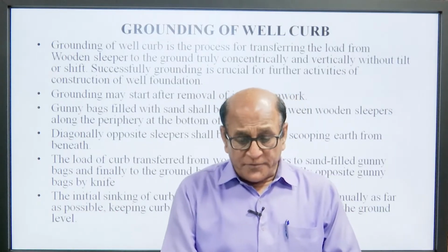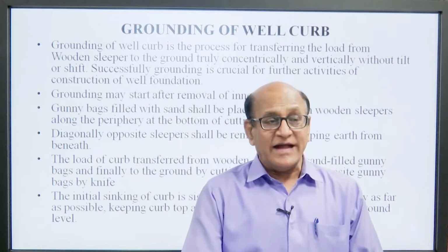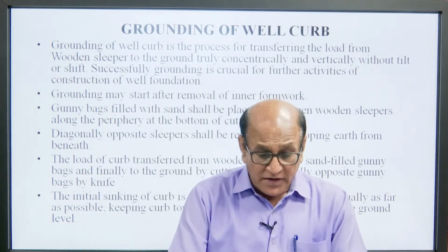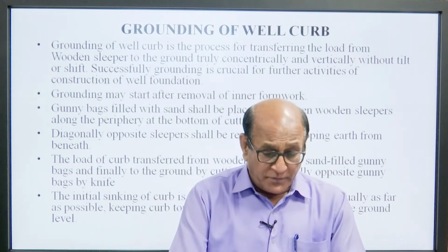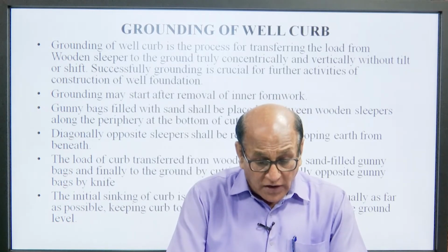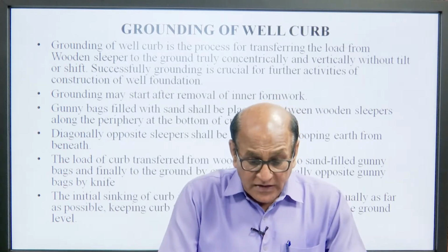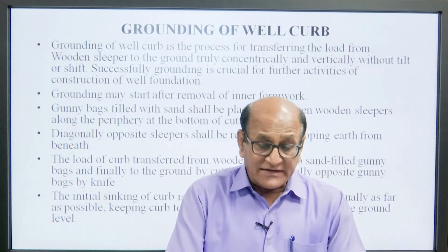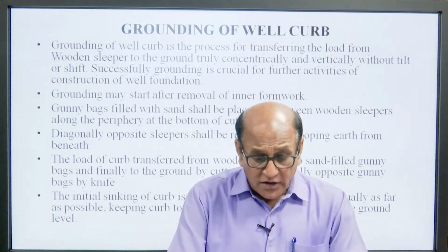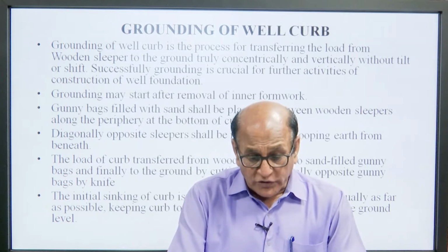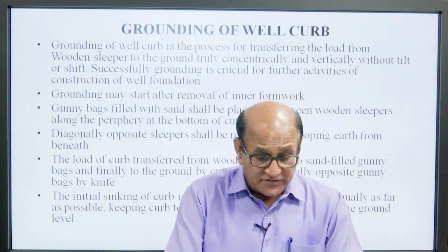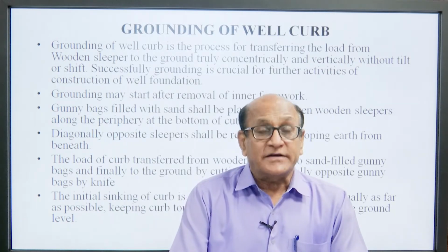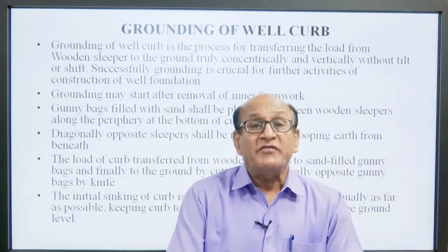The next important part is grounding of well curb. Grounding of well curb is the process of transferring the load from the wooden sleepers to the ground truly centrically and vertically without tilt and shift. Successful grounding is crucial for further activity of the construction of the well foundation. Grounding may start after removal of inner formwork.